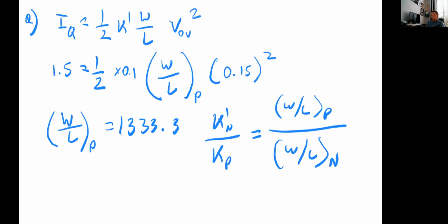That's what it means for the transistors to be matched, because what makes the K primes mismatch is the fact that the K is proportional to the mobility of the majority charge carriers. So in the case of the N channel it is going to be electrons, in the case of the P channel it is going to be holes, and the holes have lower mobility.